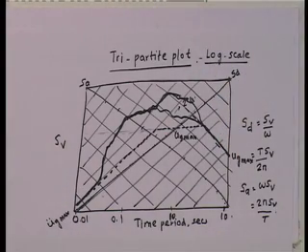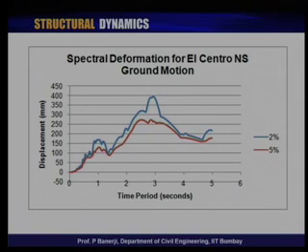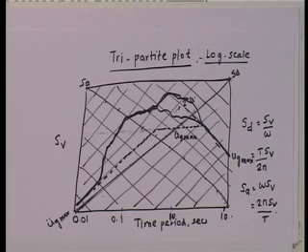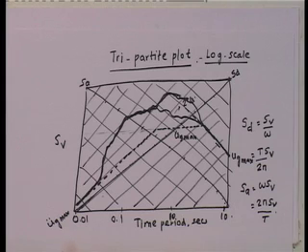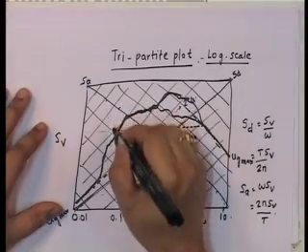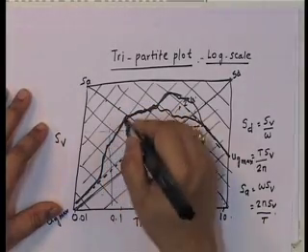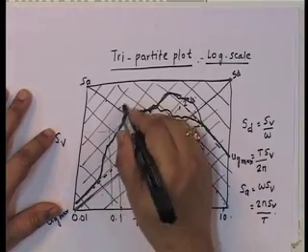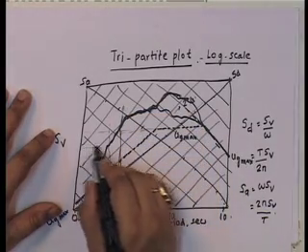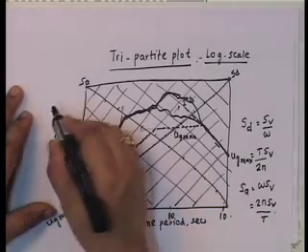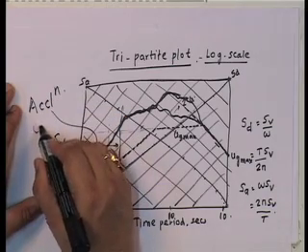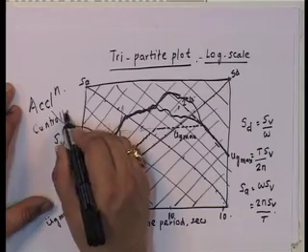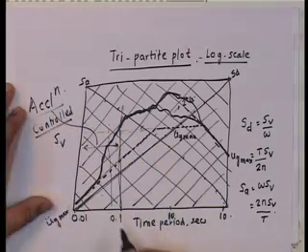So, you see all these three plots, I have plotted in one particular plot here. And it actually shows me something very, very interesting, and that is that there is a zone. Okay, this zone is about till here, where the response spectrum is acceleration controlled.